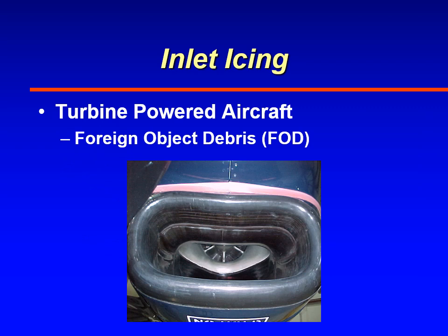With turbine-powered airplanes, it's not so much the airflow being reduced going into the engine, but it's more of a problem of ice forming on the engine inlet, and then that ice breaking off and being ingested by the engine and damaging turbine blades. This is a huge problem. There are checklist items that need to be followed that will allow you to turn on the engine anti-ice.